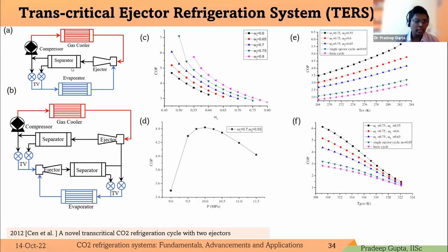So with this, I think I can explain in a better way. It's simple. Here, let's suppose the dryness fraction at the separator is H. If there is no throttle valve here, this H goes here and comes as the primary flow. The other is 1 minus H, and the entrainment ratio would be H divided by 1 minus H. Sometimes this relation does not hold true because of the ejector entrainment ratio. To provide consistency, so there is no mass mismatch, we have provided these two throttle valves.